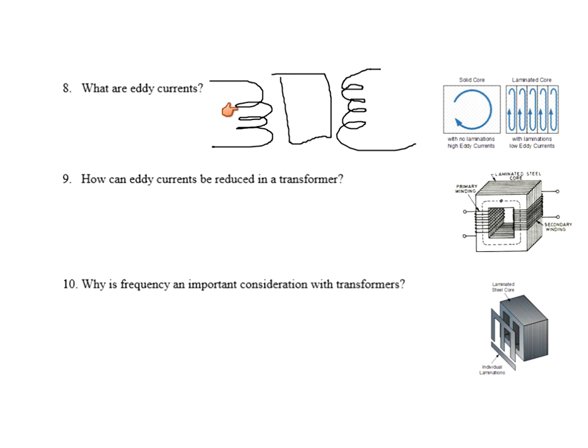When magnetic lines of flux build up here, trying to get over to cut through it, the magnetic lines of flux have to cut through the iron core as well. And guess what? You're not just generating electricity over here, but because this is a conductor, you're generating electricity inside of that as well.